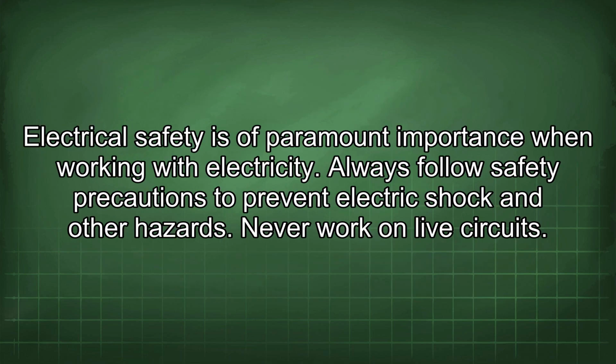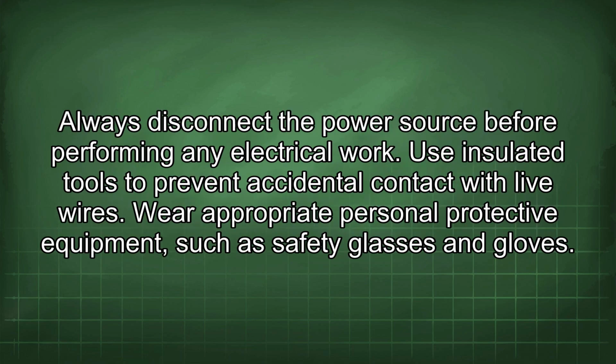Electrical safety is of paramount importance when working with electricity. Always follow safety precautions to prevent electric shock and other hazards. Never work on live circuits. Always disconnect the power source before performing any electrical work. Use insulated tools to prevent accidental contact with live wires. Wear appropriate personal protective equipment such as safety glasses and gloves.